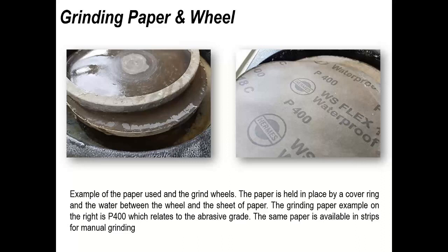So you generally start off grinding with papers between 200 to 400 and then progress up to 600, 800, and so on before you move on to a polishing operation. Remembering that the higher number is going to take off less material.